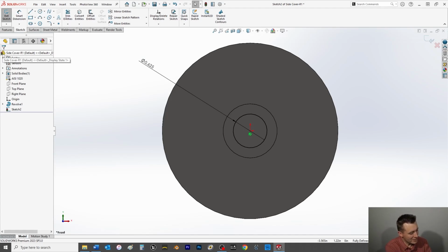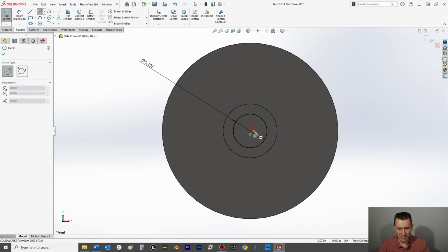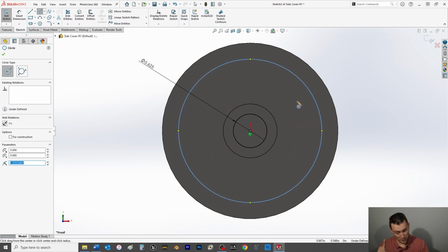And that will then take us into section 3.12, where we're going to create another circle. So come up here, click again. Again, we're going to also use the origin as the center point of that circle. And now we're going to click and drag out and click about here. But whoa, before we dimension this, we're doing something unique. We're doing reference or construction geometry here. So over in the feature area, properties, we're going to want to choose for construction on this one. And then we'll move from page 124 over to page 125, section 3.13, where we're simply going to click OK.